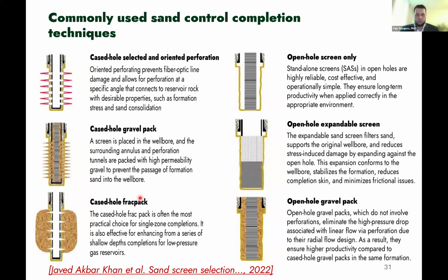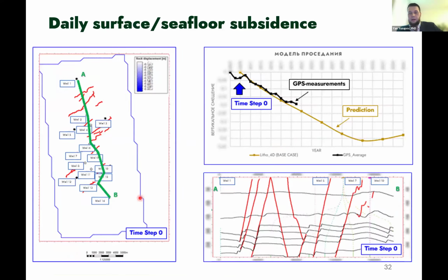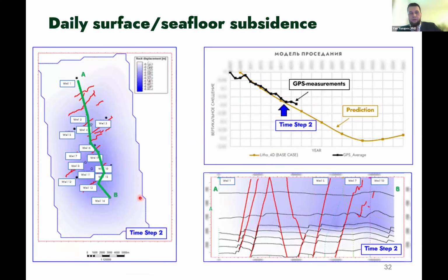And also geomechanics allows us to correctly select commonly used techniques for completion. This can be cased hole selective oriented perforation, cased hole gravel packs, cased hole frac packs, open hole screens, open hole expandable screens, open hole gravel packs.